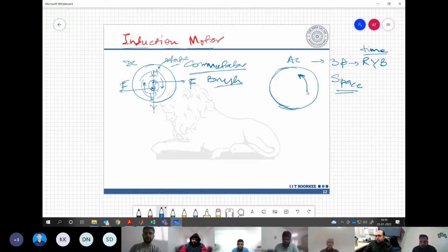So quickly we can see what is happening. Let's say there is a coil, and I draw the dot and cross, which means the coil is perpendicular to the paper or this whiteboard that you are seeing. This is the direction where the coil is going. Of course the motor is cylindrical, right? So one conductor is going like that, and then it is returning over here, and that is how the current is flowing. This is going in, this is coming out.